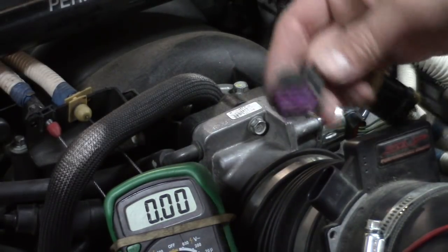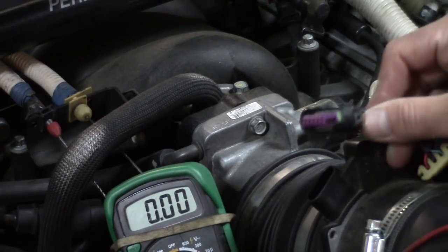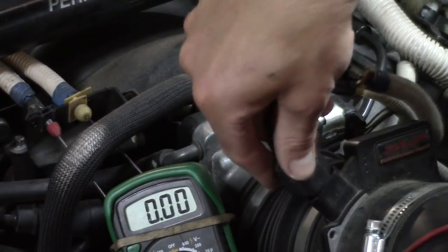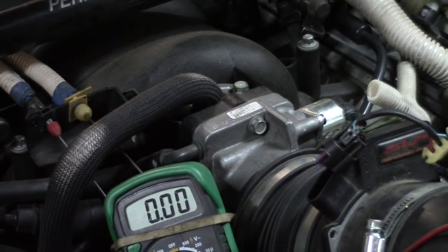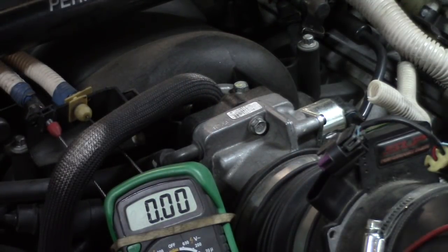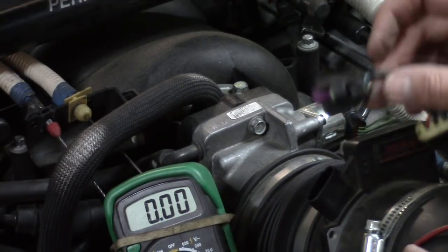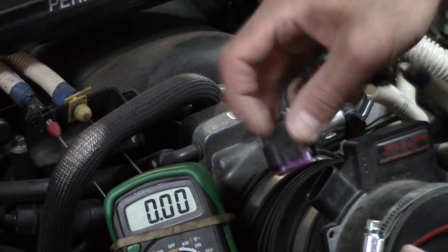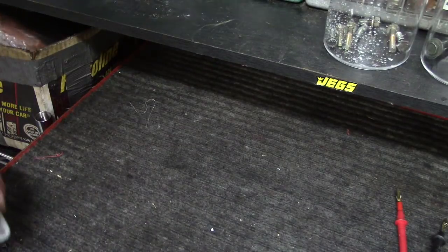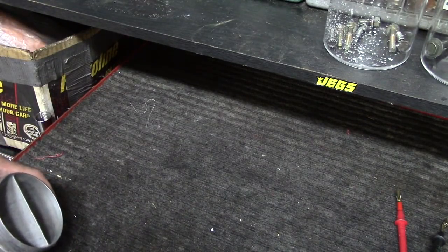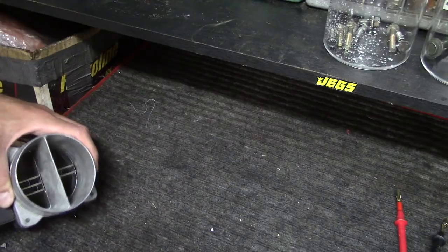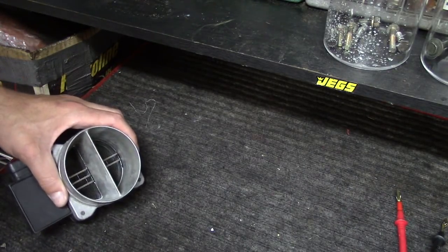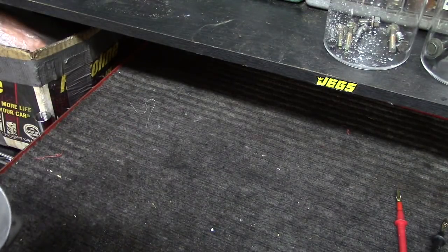But obviously the point is, whatever method you do, I think one of the easiest things to do for the MAF sensor is rule out your wiring. Obviously this one being only a 3-wire is easy. On the multiple wire sensors where you've got that IAT integrated, you will have to discern which wiring is for the IAT and which is for the MAF, and we did that in the previous video. And if you do find that you have a wiring feed issue, I do have several other videos that show you how you would trace those from the sensor on back, even all the way up to the PCM in one video, so maybe I'll put links to those.